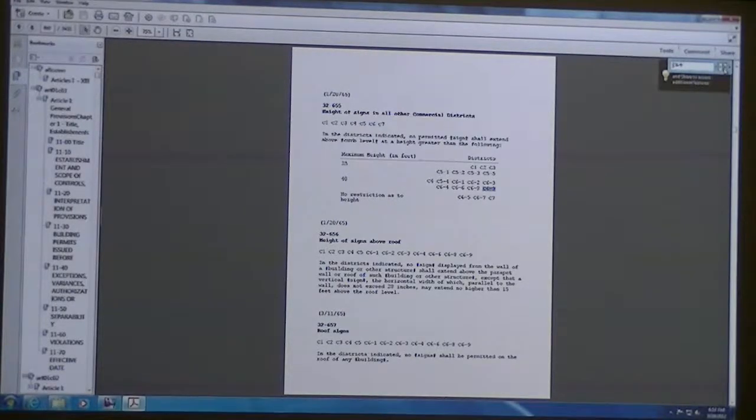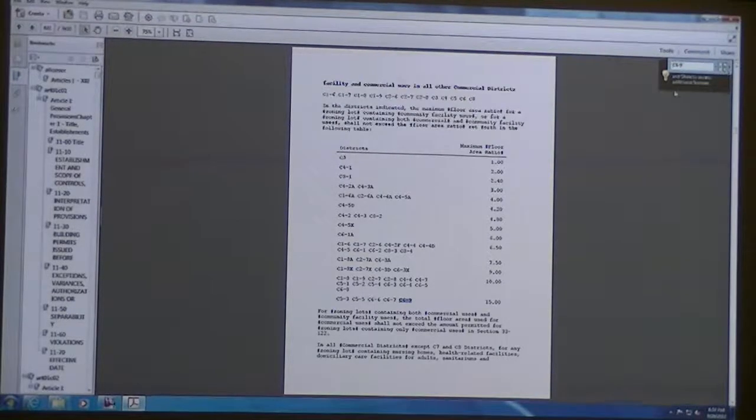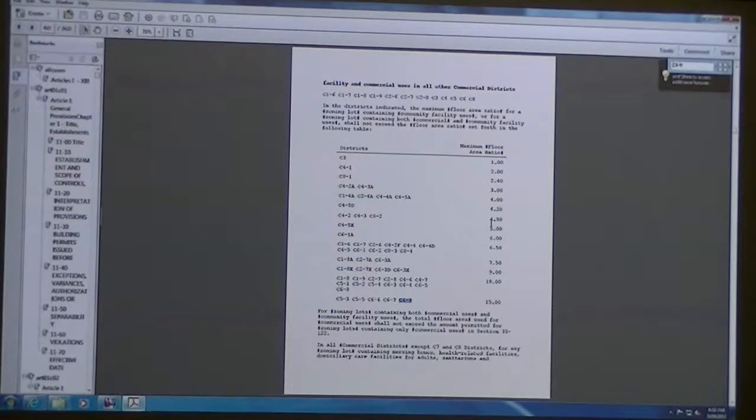Where's your site at? Midtown, well, Chelsea, so uptown from where our site is. So I was able to obtain some information like maximum height in feet, a floor area ratio, our maximum base height, our maximum building height, and then our angle for our sky exposure plane. The only thing I could not find was our actual setback, so I'm just going to apply some common knowledge setbacks to our site.